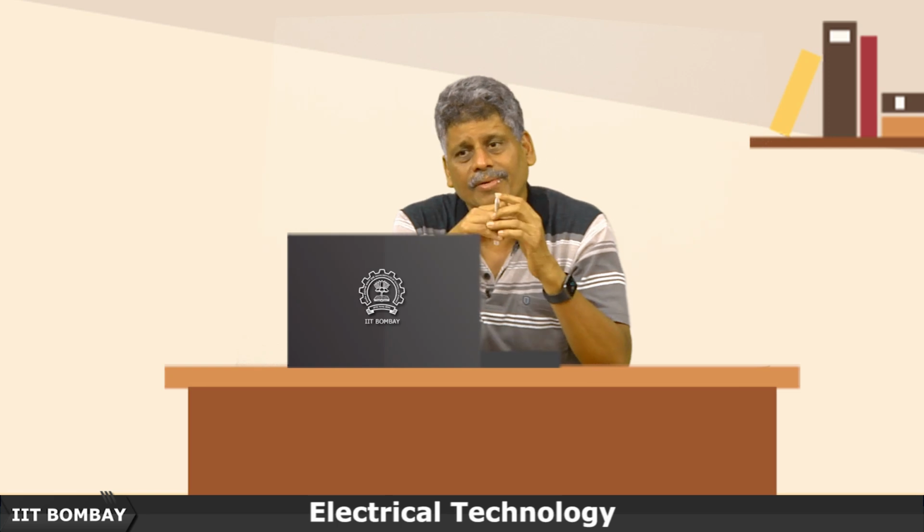Its load may be say around 10 megawatts or something like that, but the transmission levels would be carrying, as I said, 600 megawatt, 2200 megawatt. So, you do not need that voltage level when you are dealing with distributing electricity in some 400 acres, 10 megawatts. Then you can work with 22 kV three phase system, and that is why the distribution systems work at a lower voltage level.